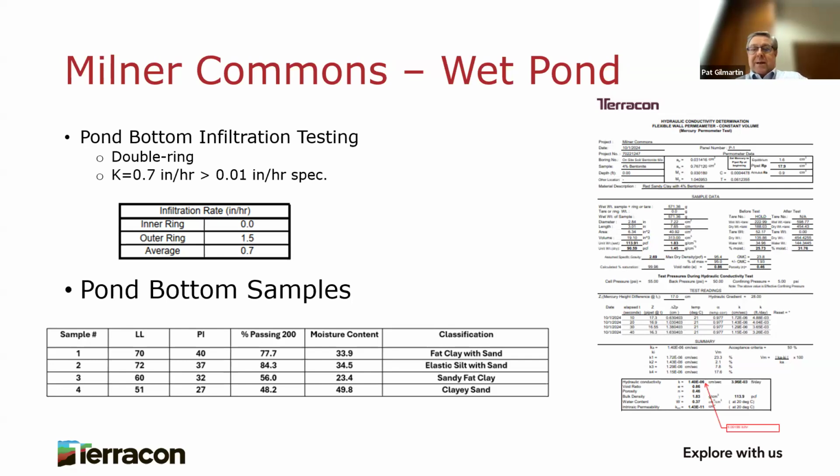So we did a quick bentonite mix design, and they imported some other soils because they didn't want to mess with what was on the bottom of it, and mixed some bentonite in it. And we ran an infiltration test again, and it was less than 0.01 inch per hour. So we all concluded, yeah, this pond will hold water like it's supposed to.